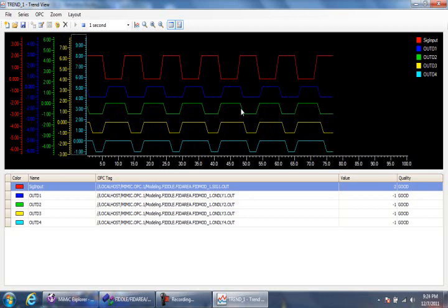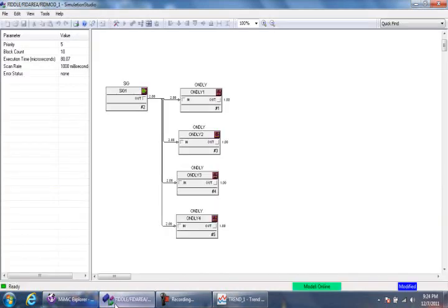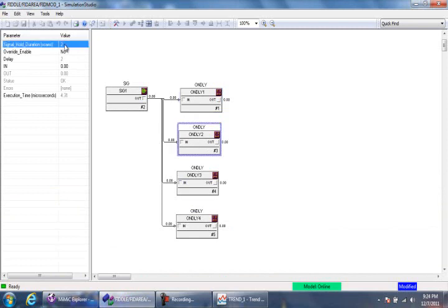So basically when it goes from low to high, the delay is causing it to stay high for a longer period of time. As you can see, the one that I've got for a time period of 4 is staying high the very longest when it transitions from low to high. So that's what changing the signal hold parameter does. It changes how long the signal remains high after the input signal transitions.